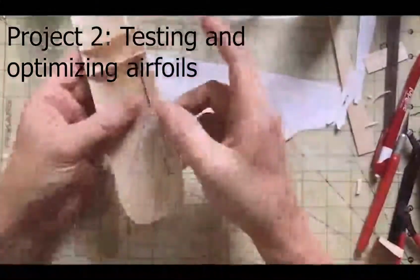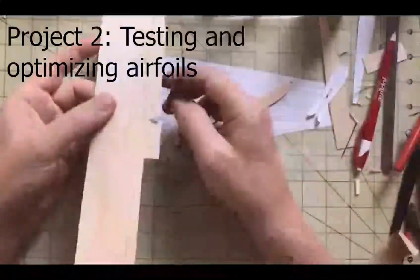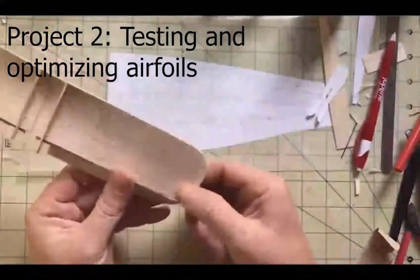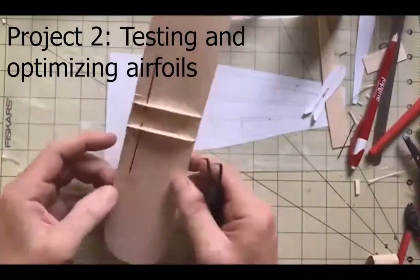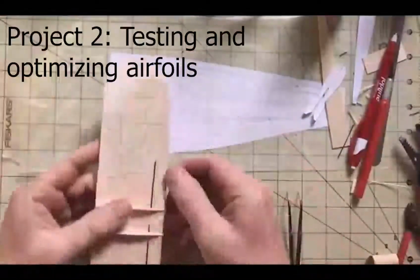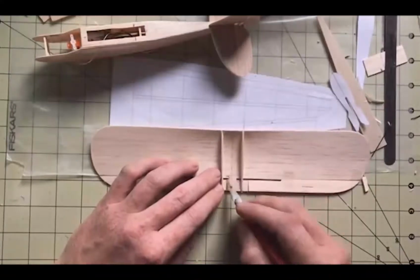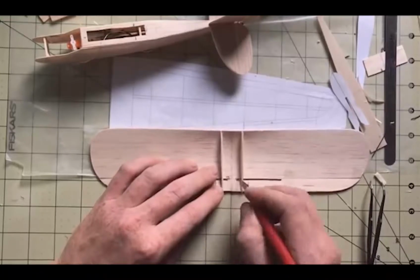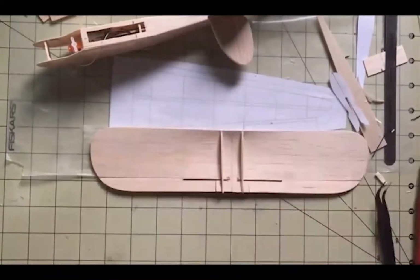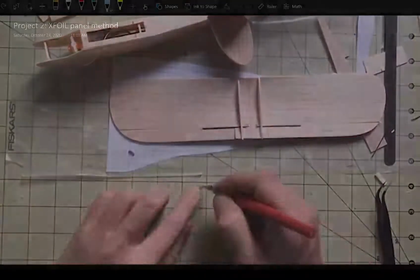Often, engineers look for fast and efficient tools that can accurately tell them about the performance of a given aerodynamic shape. This lets them compare many different shapes and optimize for some desired output parameter. One tool that's widely used are panel method solvers, which we've studied in the past. In this project, a computer program called XFoil will take center stage that uses the Vortex Panel Method combined with a viscous flow, turbulence, and separation models to give accurate performance data.